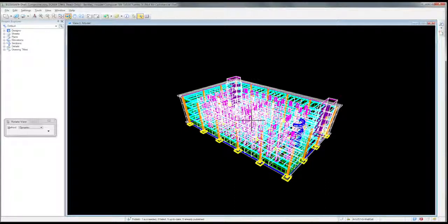It tells us we succeeded, nothing failed, everything's up to date, and we now have an I model created out of the AutoCAD DWG file that we started with. That's really all you need to know as a minimum about I Model Composer or creating I models from a MicroStation file. Of course, there's much more.